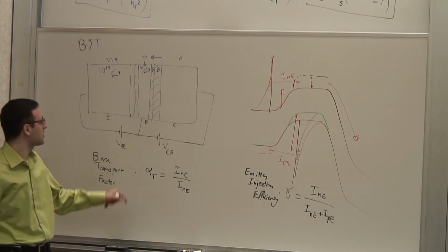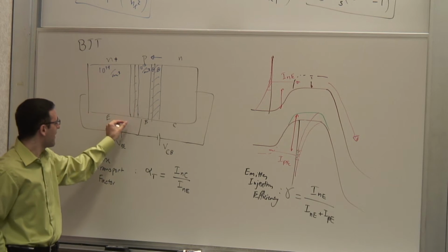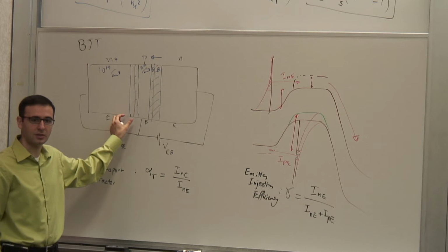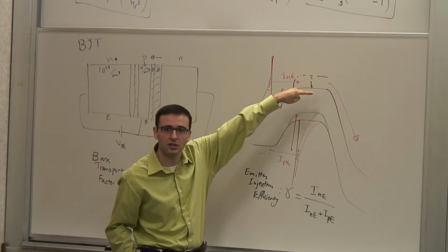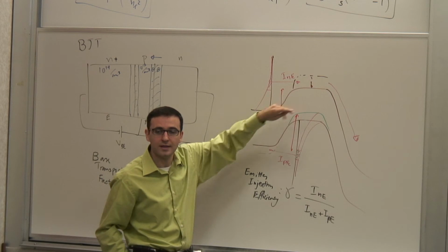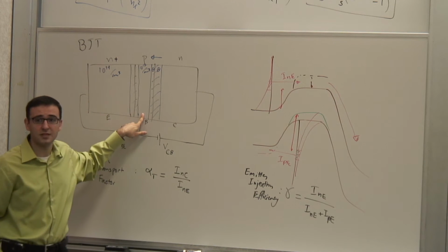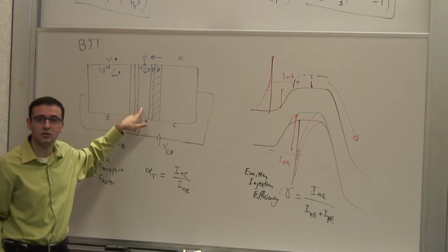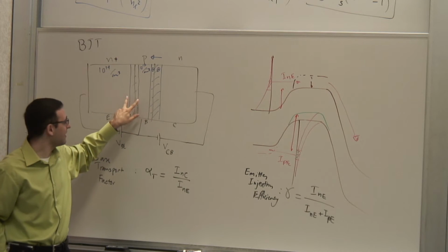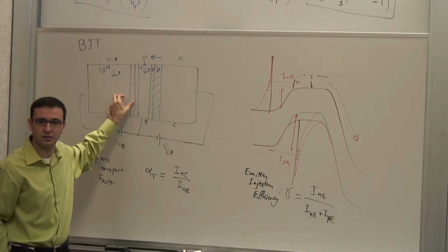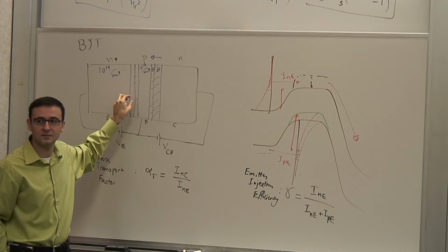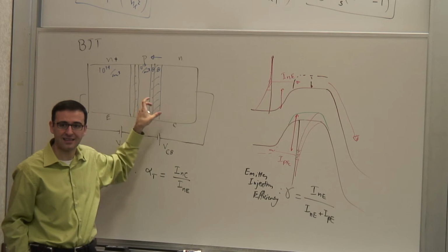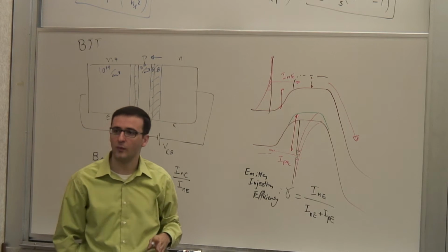The other thing is that it's also a very sensitive point, because a slight change in this voltage, remember, can result in a substantial, exponential change in the current, right? Now, any physical resistor has noise, as we'll see later on. So the noise of this resistor directly appears across this junction and modulates its current. So from a noise perspective, that's a bad thing too. And we'll talk about this extensively later on when we talk about noise.